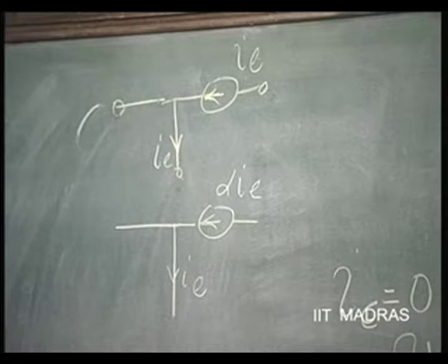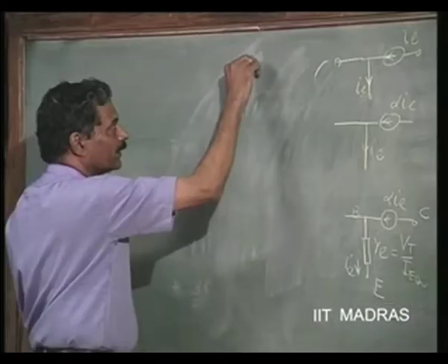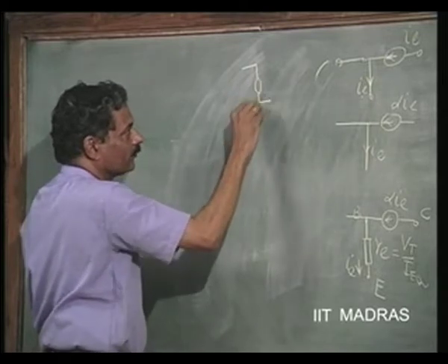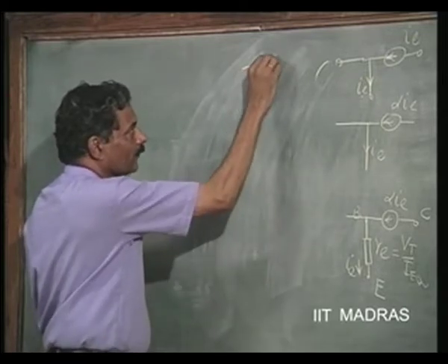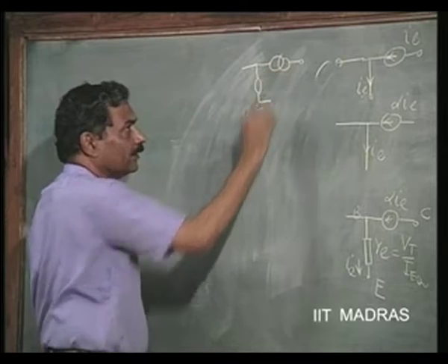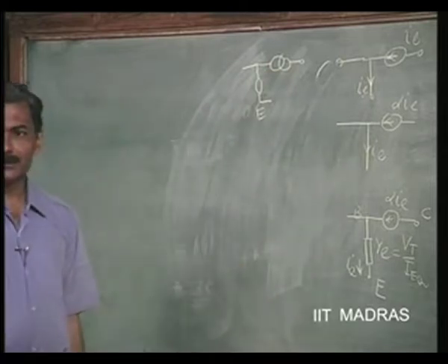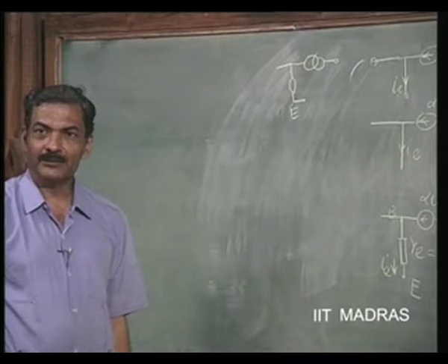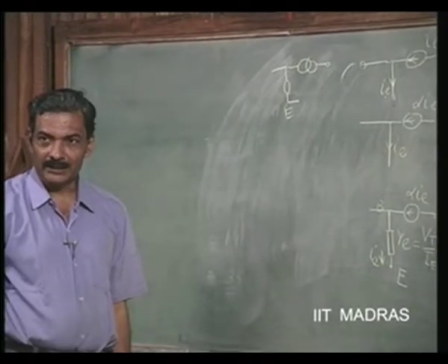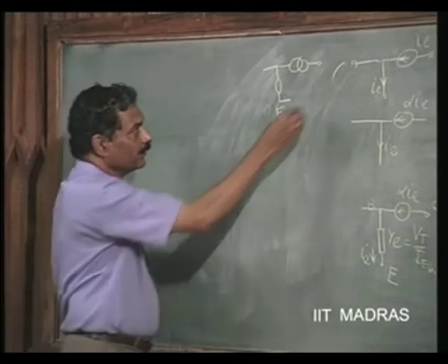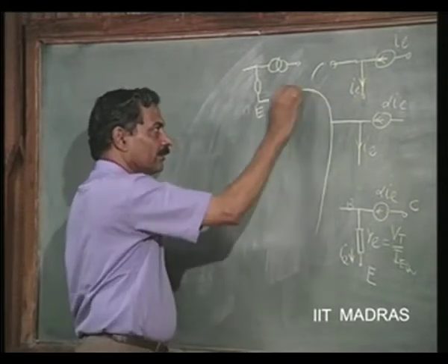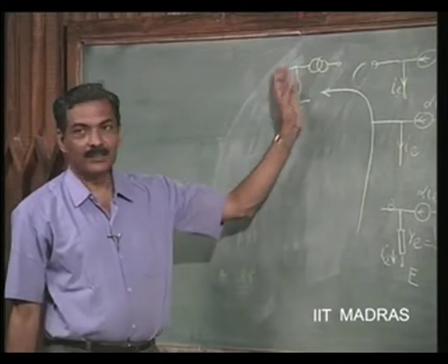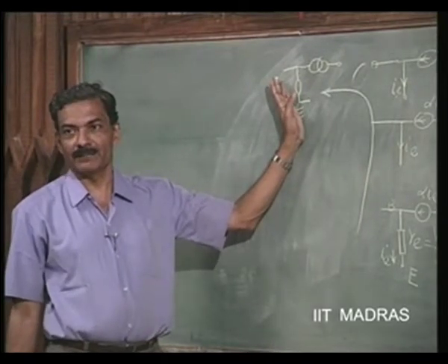Therefore, between these 2 points you represent it by a nullator, and here this is a norator. This is a source which can give you any current, and across it any voltage can be sustained. So, this is the route to the ideal network representation of a transistor.